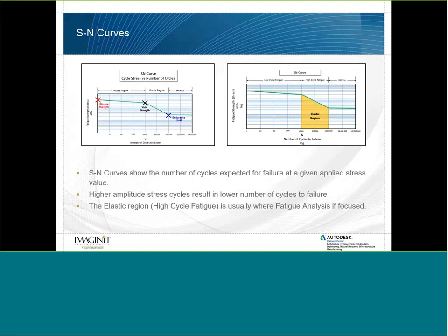Maybe after 10 to 100 cycles, we're not going to see a huge decrease in our overall stress. But when we start talking about getting to 100,000 cycles, 200,000, 1 million cycles, the maximum stress that the material can handle will start to degrade, and this will follow this SN curve. This is created through basically a series of tests to build this data.